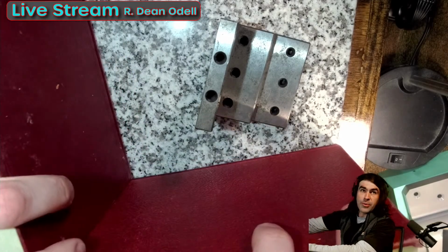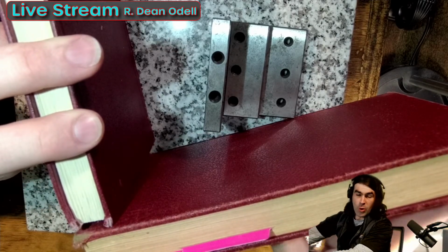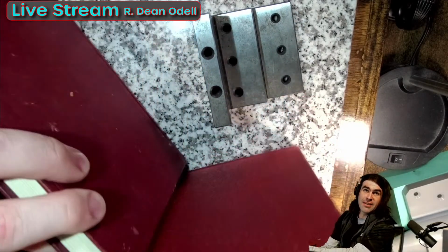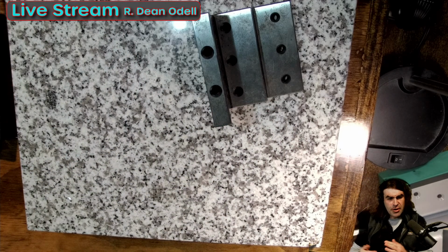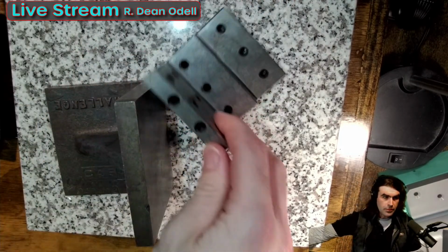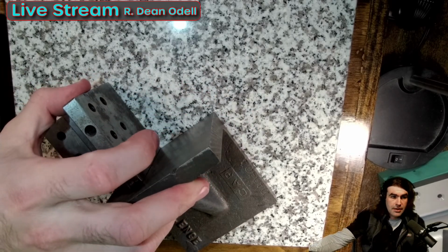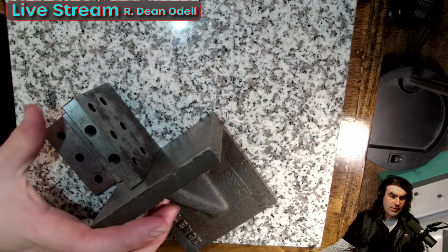So whether they're 90 degrees to each other at this corner, or, as in the case of a center plane, they're 90 degrees to each other like this, they've still got to be that 90 degrees. So that's why it's to datums A and B, and you end up with something like this, where this one's 90 degrees to the table, this one's 90 degrees to the table, and 90 degrees to this.